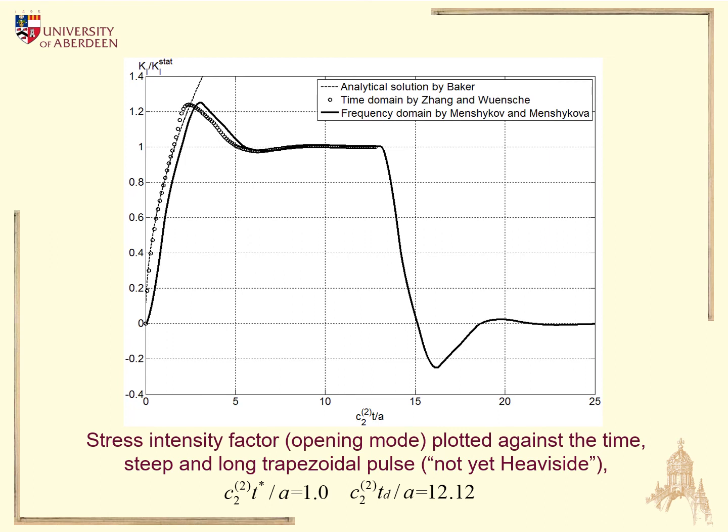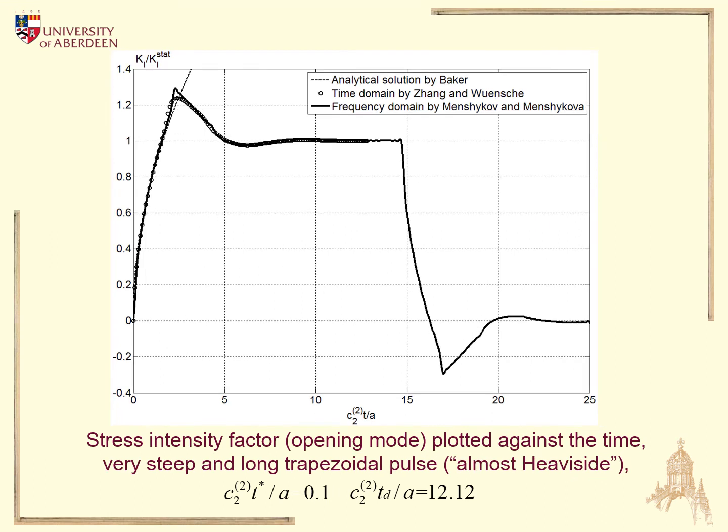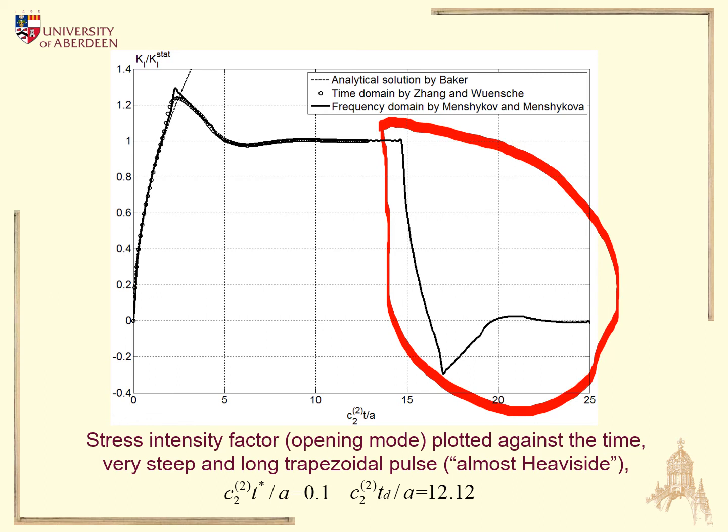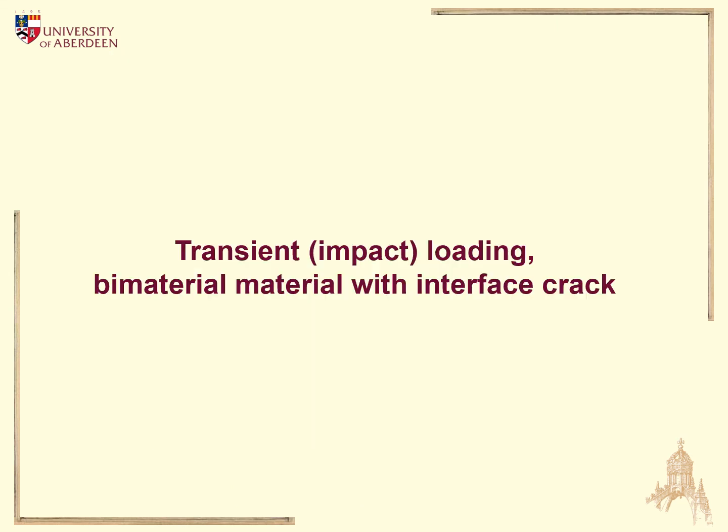But if we make our pulse even steeper, then we have almost ideal coincidence, which means that we can easily disregard this part because we need this part only to get a repeated loading, and we just focus on this bit. So it's possible to solve dynamic problem for any type of the loading using solutions obtained for frequency domains.